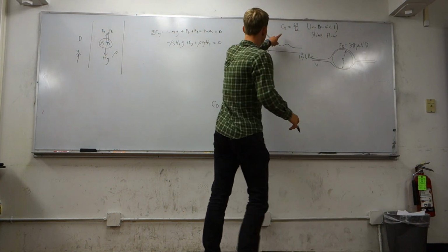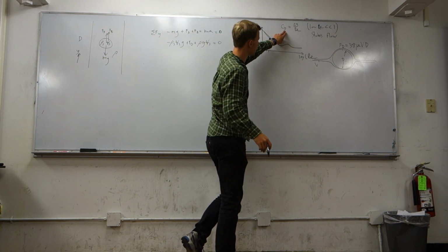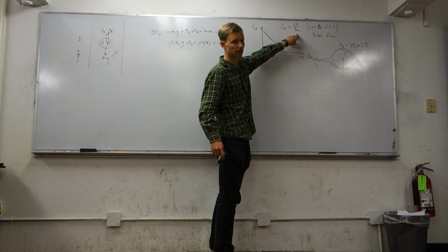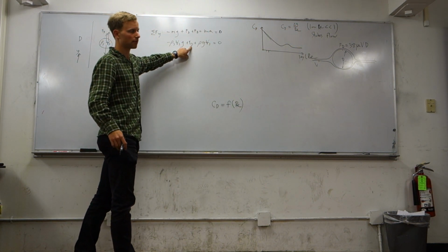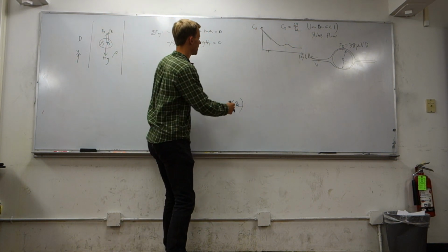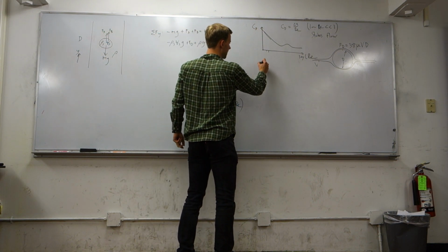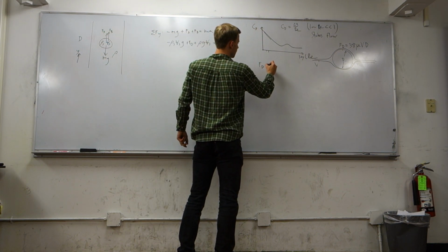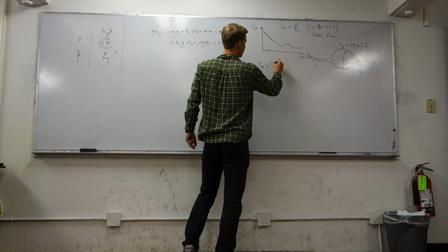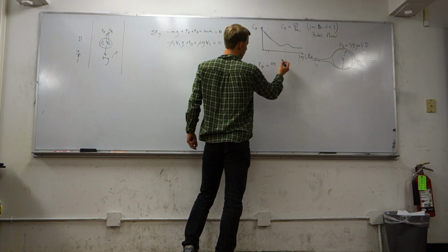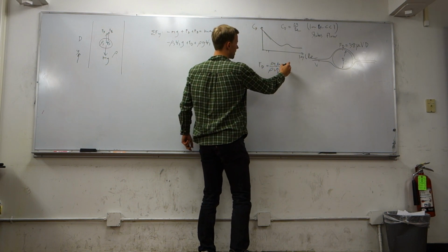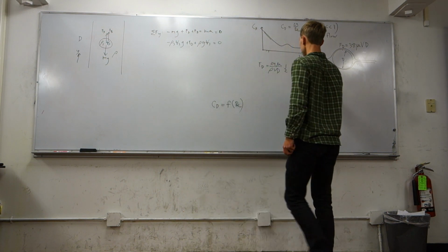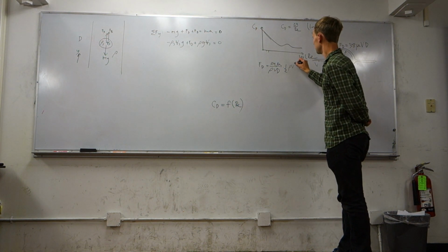So, given that this is true, I'm going to plug in for what the drag force is, the drag coefficient is, and what the Reynolds number is, solve for the drag force, and then plug the drag force back into our problem. So, coefficient of drag is Fd over 1/2 rho v squared A, which is equal to 24 over the Reynolds number, so mu comes to the top, rho v d in the denominator, and I have 1/2 times rho v squared.